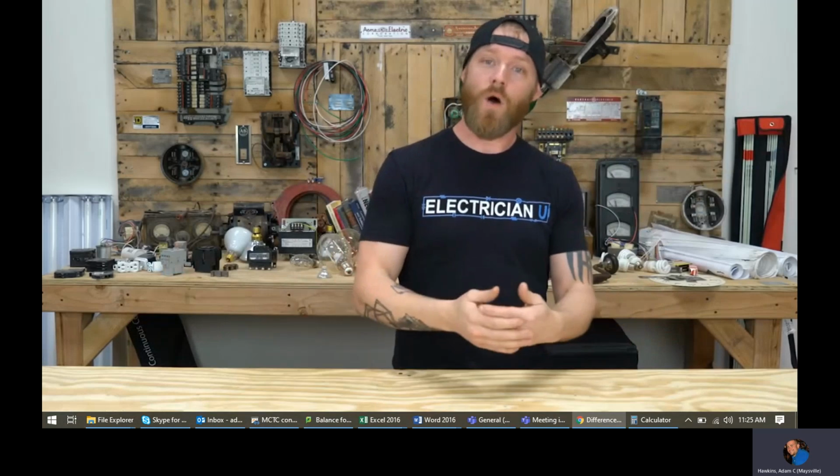Sometimes in different factories and buildings, you're going to have motors that require a little bit more torque, and so they're going to need a Delta service rather than a Y. Something that has a whole bunch of lighting loads specifically is going to do better on a Y configuration because you're going to have a neutral with it as well. So there's reasons why, and again, I'm not going to get into all that in this video, but I just want to break down how these voltages are derived and what they mean.